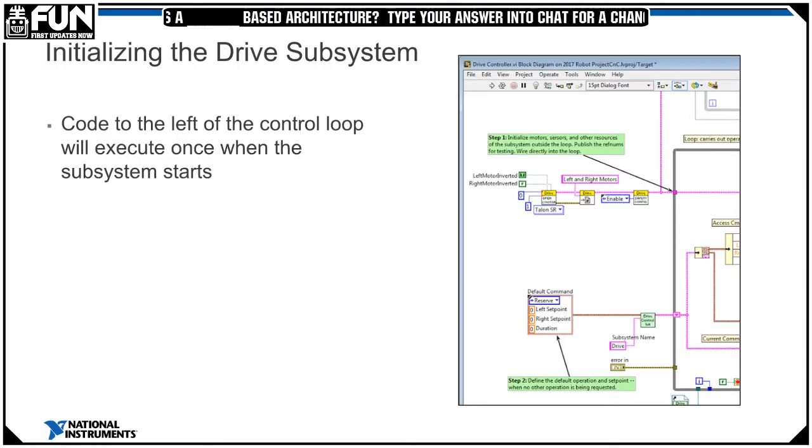You can have the same named operation in different controls, in different subsystems. Again, the setpoint control just contains all of the data fields that any of your modes in your subsystem or your commands might need. So if you have a set point and a duration and a height, you would have to edit that to add the height in because that's not default.